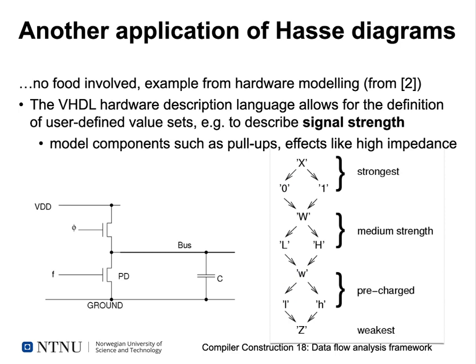But of course, if we have a direct clash of logical levels of the same strength, so if we have a 0 and a 1, then you can't compare these. And in real life, you have a short circuit. You might even destroy your circuit using this. And this is a typical example for such an application here.